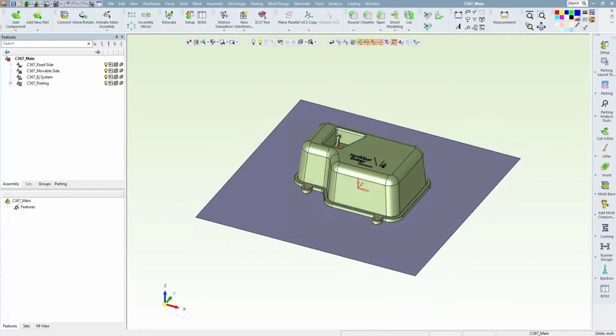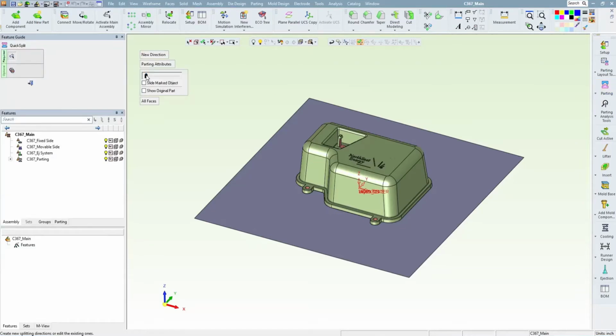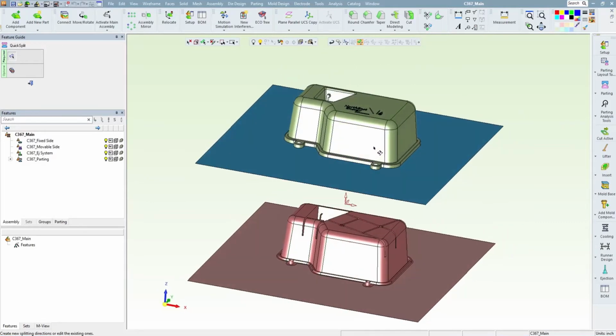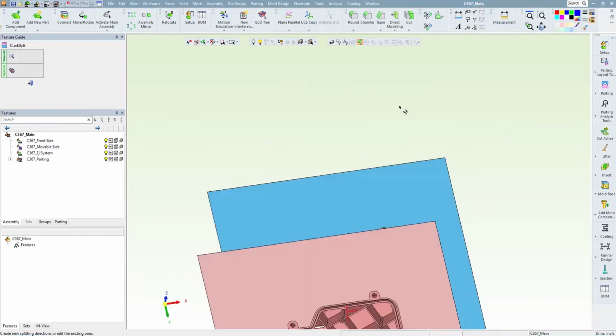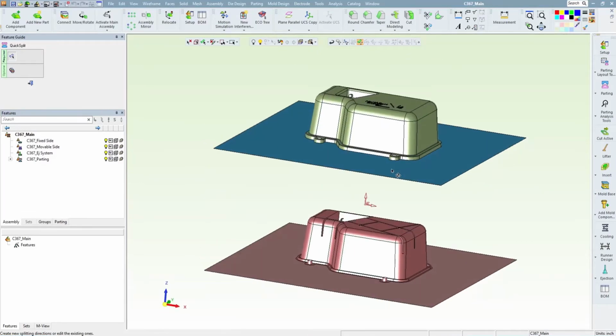Of course, usually you aren't thinking about little mold inserts when Quick Split is being used at the very beginning of the job. This is generally when you're thinking about the main cavities and parting lines. But if it's an obvious area or a larger area that you know from the start will need to be inserted, defining it in Quick Split is actually a very nice way to go.